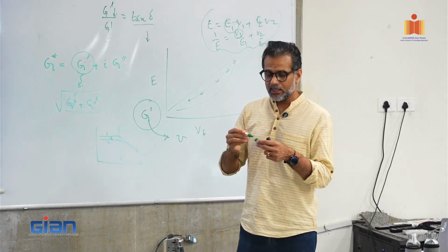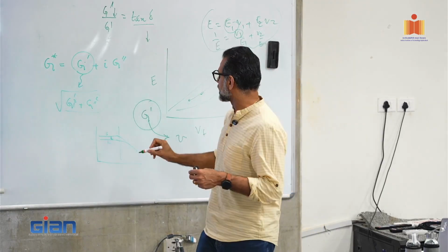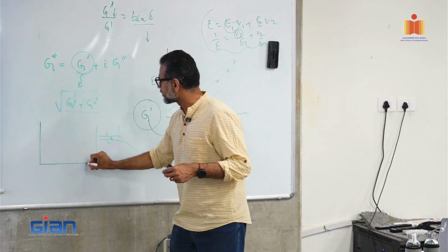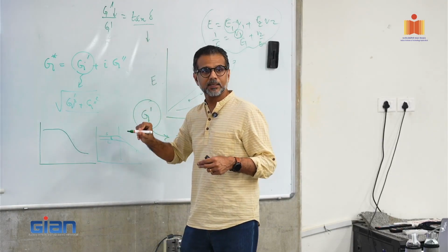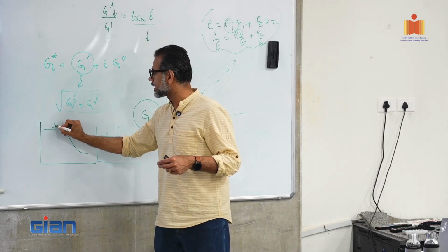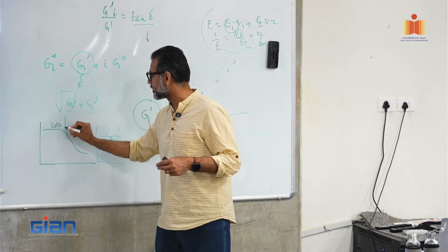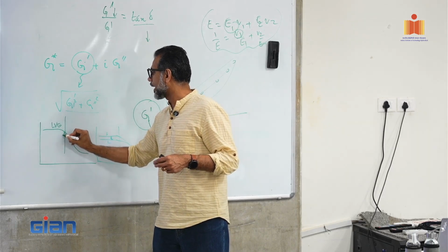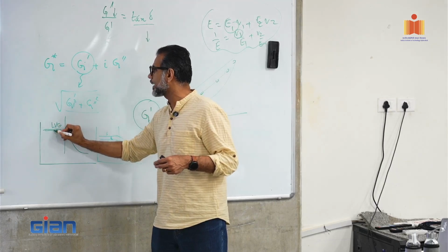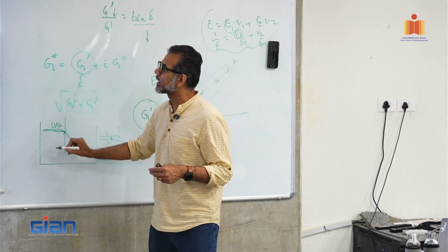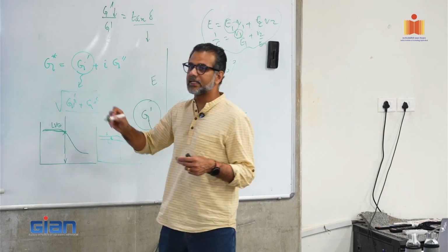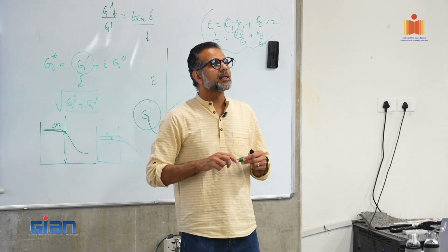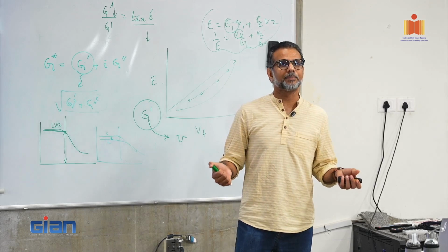Critical strain signifies the end of the linear viscoelastic regime. If you remember yesterday, you have the curves going like this, correct? This is your linear viscoelastic range. This is your solid-like behavior. The end of this plateau range is your critical strain, which you can indicate as the strain that is the deformation capacity of the specimen.